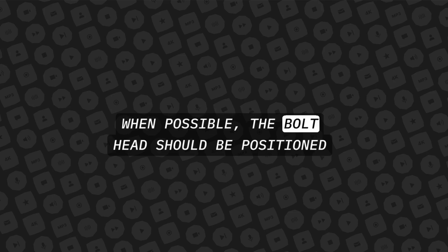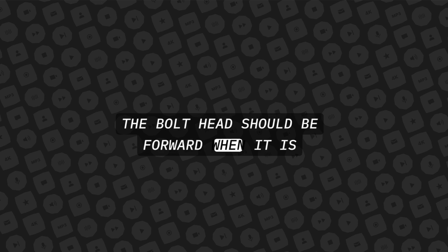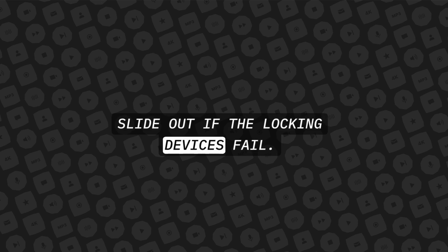When installing an aircraft bolt, what precautions would you take regarding the position of the bolt? When possible, the bolt head should be positioned on top when a bolt is installed vertically, and the bolt head should be forward when it is installed horizontally. In these positions, the bolt is less likely to slide out if the locking devices fail.